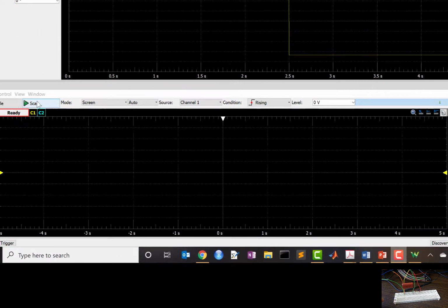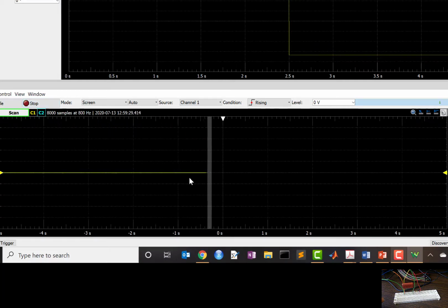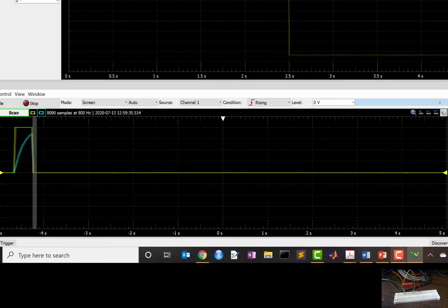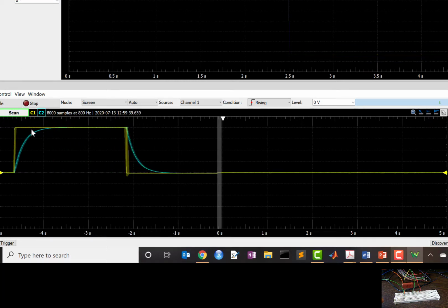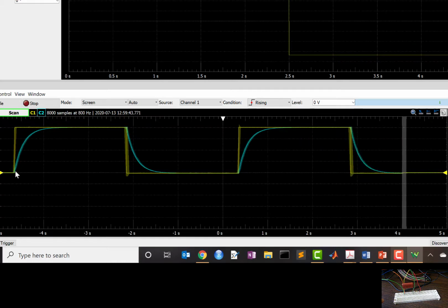Are you ready? Well, let's start off by looking at how the voltage of the capacitor looks without any input. It's 0. Surprise, surprise. Now, if I turn on my input, notice that immediately, during this period where I'm supplying a constant 2 volts for 2.5 seconds, the output, this blue curve, starts to rise exponentially fast towards that.